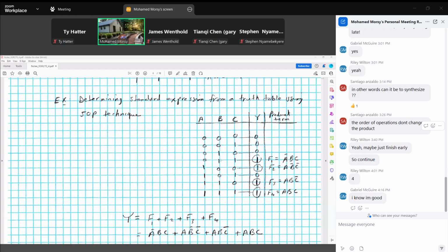You use B. Why don't you use B inverted? Because it's already 1. Perfect. We need the multiplication to be 1. If I use B inverted, B will be 0, so the product will be 0, not 1. So definitely we use B because B is 1 already. We use C because C is 1 already. We use A inverted because the input A is 0 here.